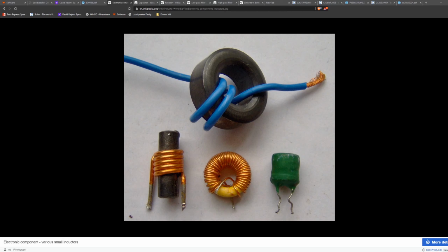When using a core in an audio crossover, it can lead to saturation under certain situations, and when a core gets saturated or too much current goes through the inductor, its inductance will actually reduce, and then it will lose the benefit of having the core and act as a straight wire. And this can cause all kinds of distortion in an audio system. So usually it's better to use an air core inductor because they cannot saturate and will remain the same over any load.